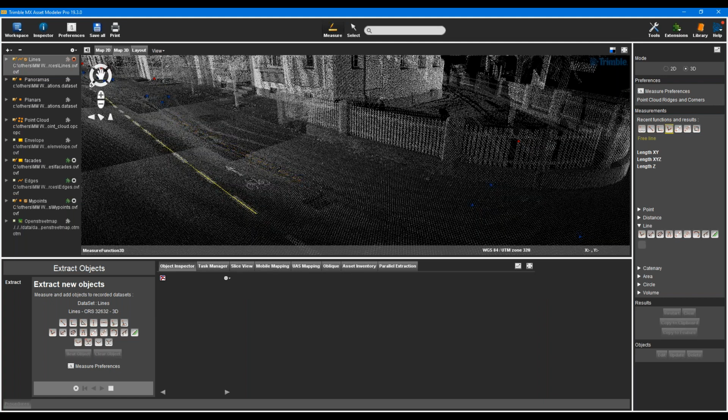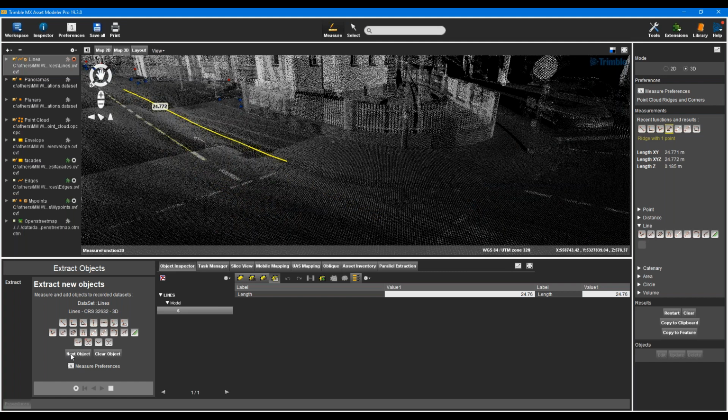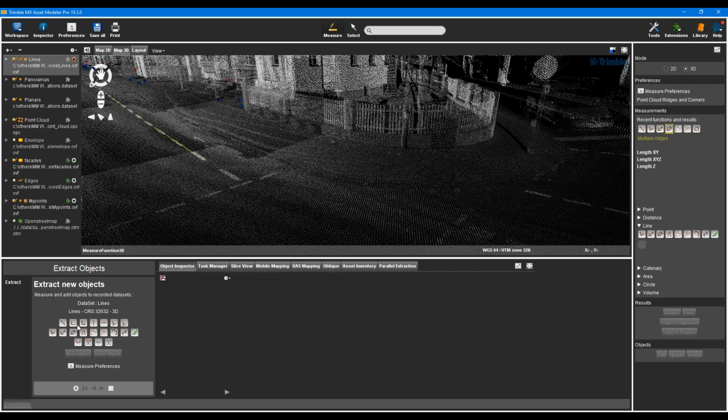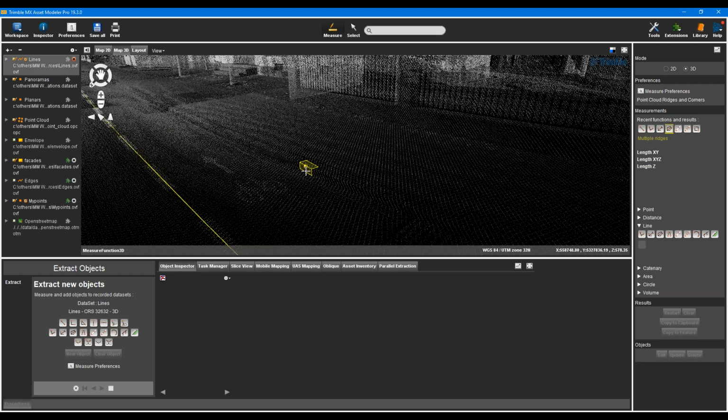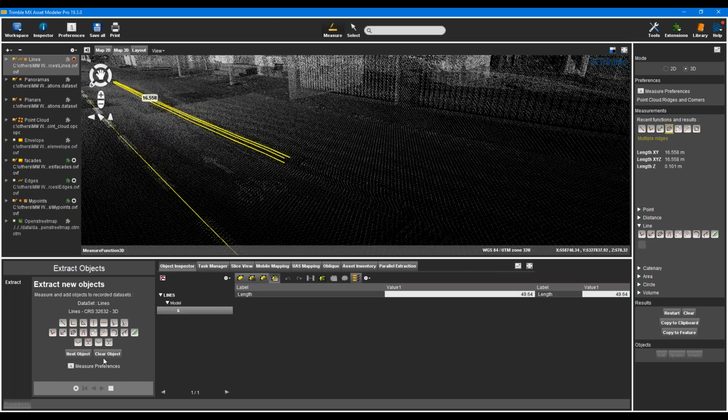It's also very nice to combine this tool with the semi-automated curb extraction or ridge extraction with 1 point, by simply letting this point run, and it will simply extract the ridge of your pavement, like so. And you can go to the next object. In addition, you could also use the multi-ridge tool, which lets you extract not only 1, but maybe also 2 ridges together, or even 3 of them. And let the tool run, and it will simply extract 3 lines representing your edge.